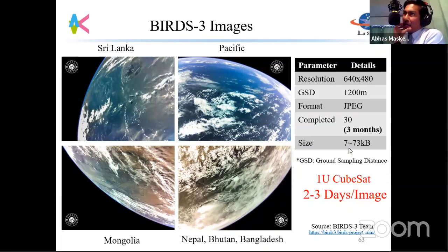So my way of doing it, especially with LDOs, is that if you are starting out, it's better to look at what other people have used. So look at the BOMs. I would not suggest you find an LDO by yourself, like going to a website and searching for LDOs at, let's say, 3.3 volts.